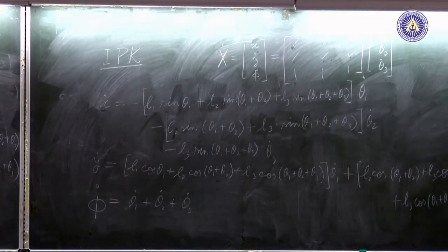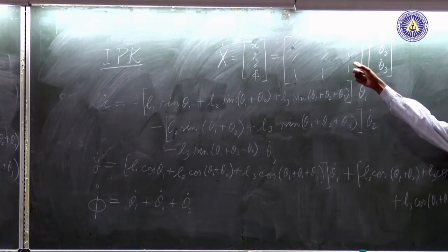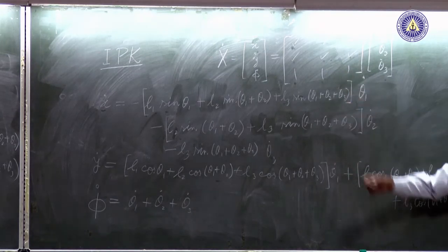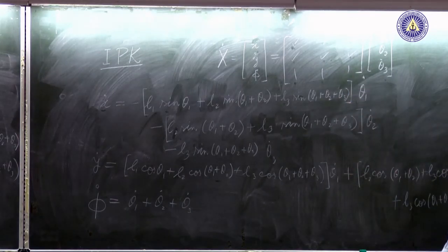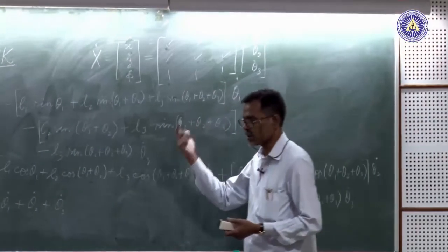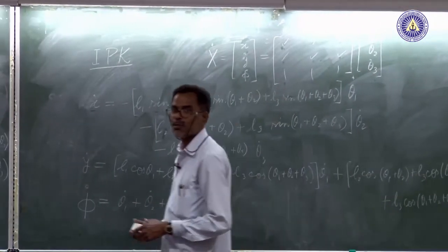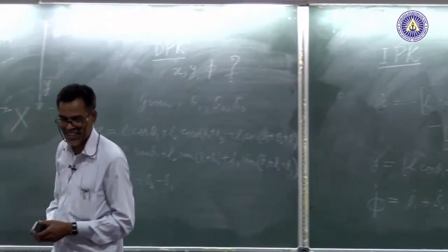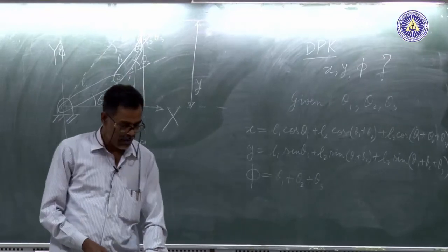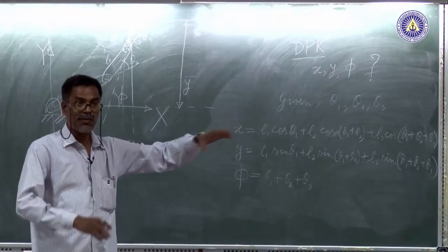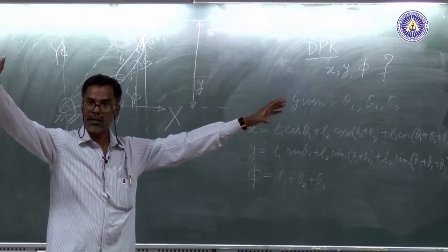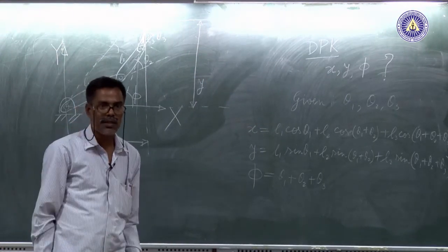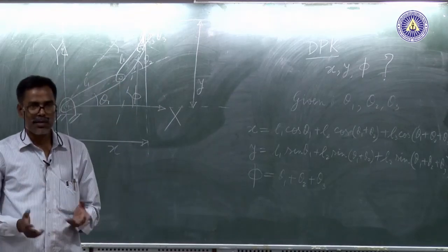Jacobian, that is it. This matrix is a Jacobian, and that is why the matrix that you formulate out of this is the Jacobian matrix of the manipulator. So, manipulator Jacobian we have constructed. So, tomorrow we will start from this point, from Jacobian. And that same Jacobian you can frame for a 6 degree of freedom case also. That Jacobian will be 6 by 6 matrix with huge things inside. Okay. So, I think we are through almost.